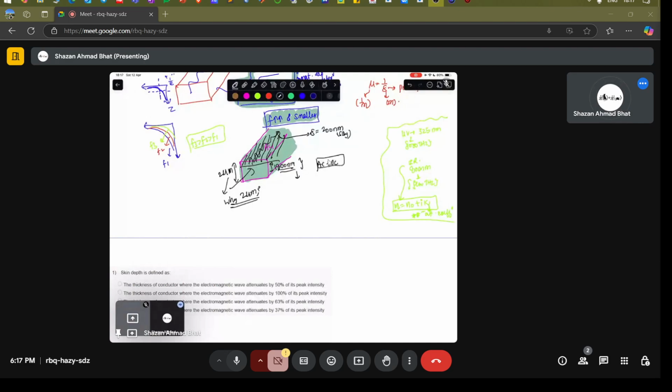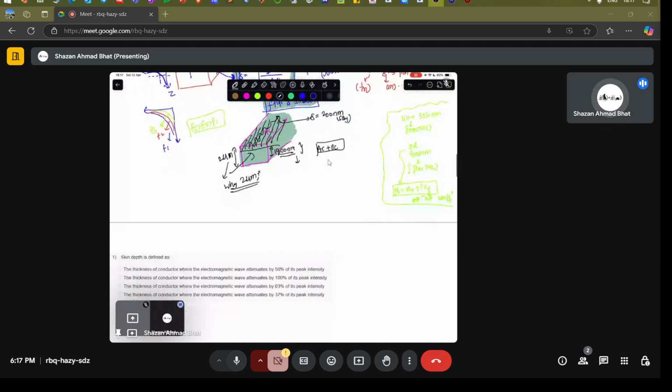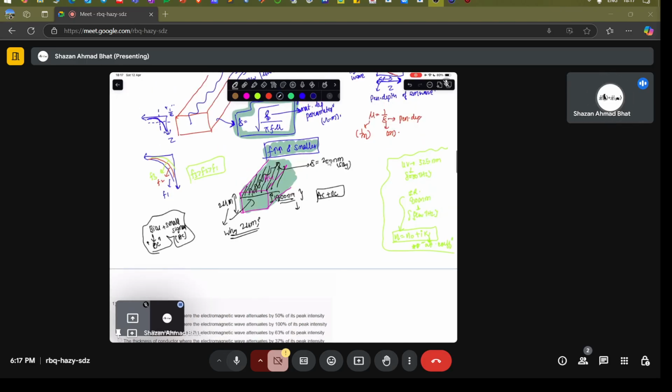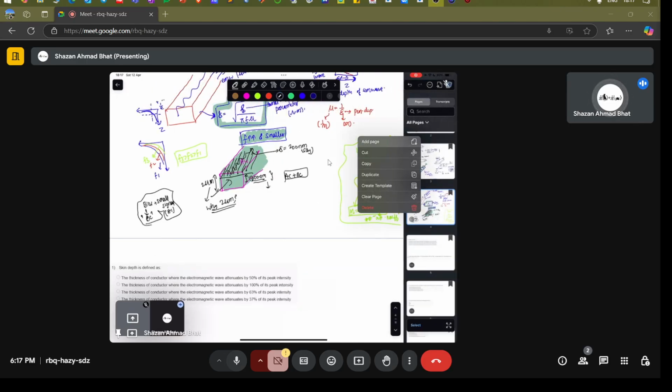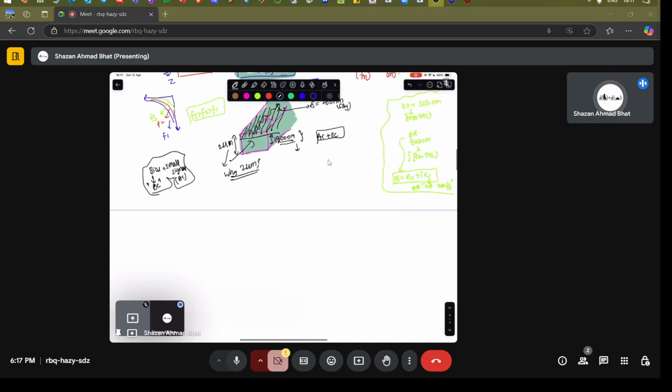Just like, if you remember, for example, you give a certain bias plus some small signal. This small signal is AC, so this bias is DC. So these metallic lines have to carry both AC as well as DC currents as well as voltage. So that's why you need to design the metallic wires accordingly.